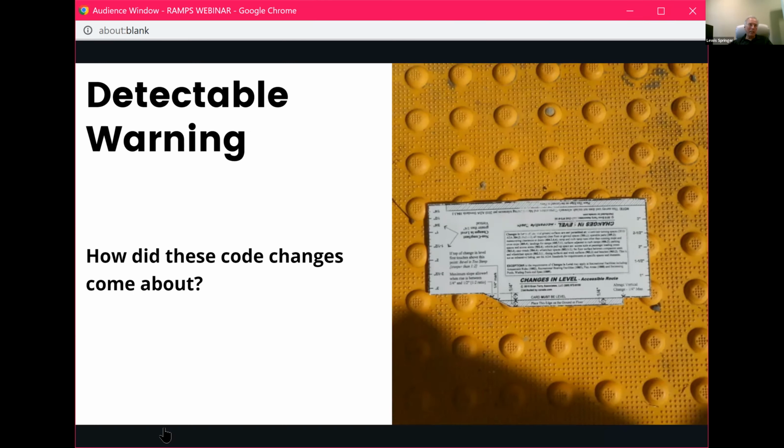So where those two meet, you're supposed to have a 4-inch vertical separation, and this is not only on a defined accessible route, but it's on any defined pedestrian route. So if you're walking through a parking lot or a parking garage, down a drive aisle, those are not defined pedestrian routes. So that doesn't apply, but anything that's a defined pedestrian route needs to be raised.